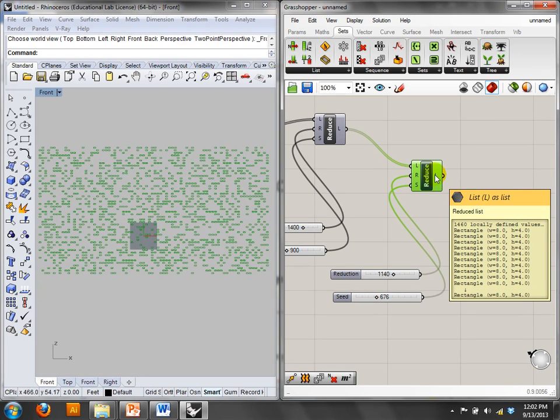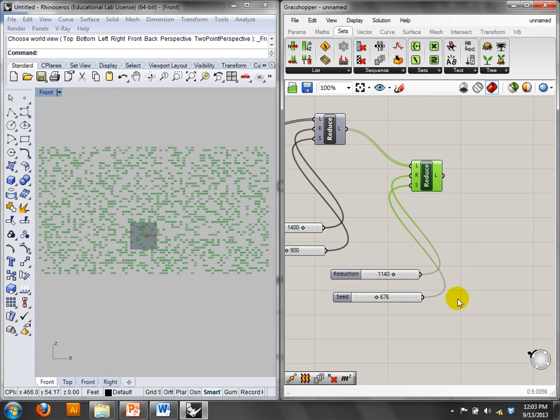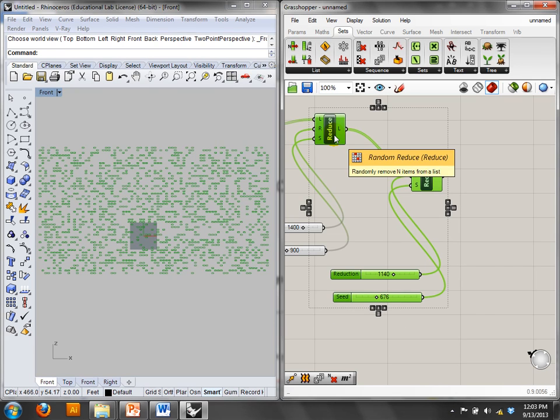Mason: Can you set up parameters like if you wanted to make a brick wall so that they're always touching each other, so that it would be much less stable? Yeah, I mean, basically, like in the example that I gave for homework, right? I did a cull where I removed every other one, and then I gave them spacing. If you got the right proportions, like the size of the brick, you could do a pattern cull.